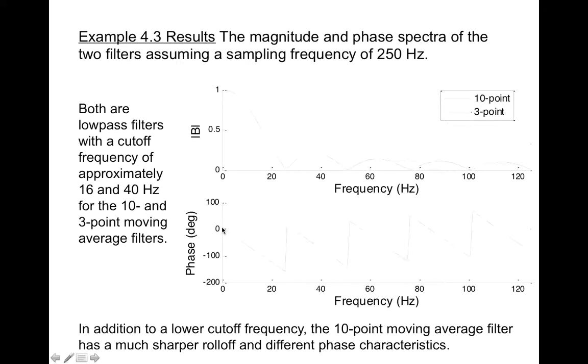What that is in MATLAB: when you get to negative 180 degrees, it shifts you up to 0. So the phase doesn't really look like this zigzag plot. It's actually continuously declining. It's just that when we do 180 degree rotations, the way MATLAB resets itself is it resets back to 0.